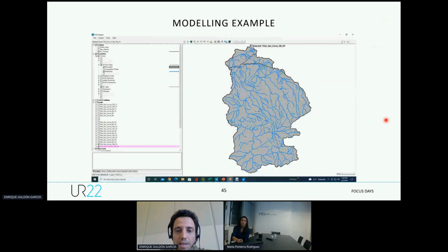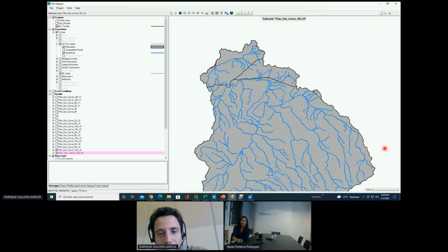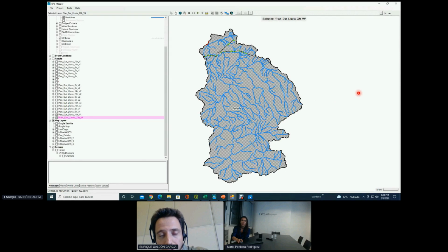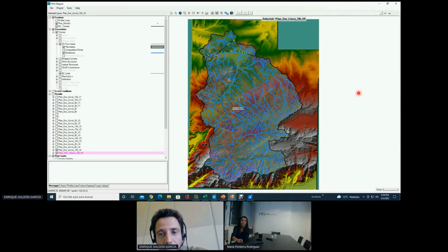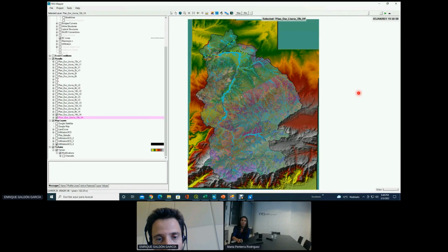Well, here you can see an example. Here in black, you have on the top the railway line that goes over here. In blue, you have the river network. The green that was appearing there are the different intersections of the railway line with the river that define the concentration times. And obviously, we are basing everything on digital elevation models, and we use together with that infiltration and roughness information layers to run a simulation that represents a physical-based model of how the flooding occurs